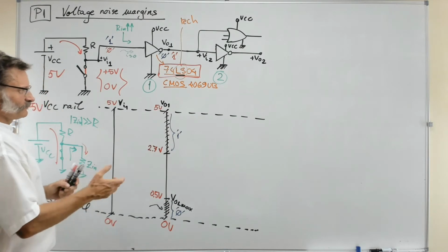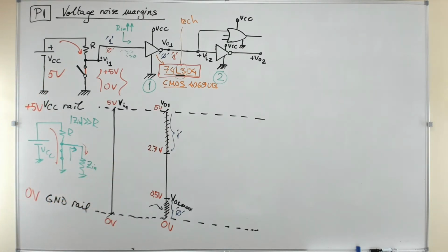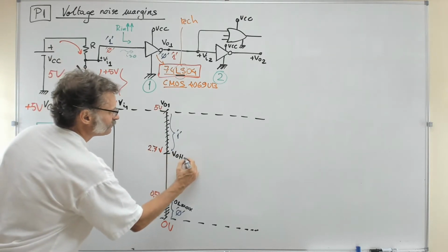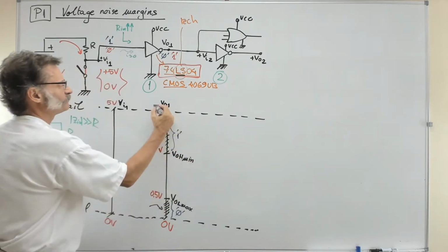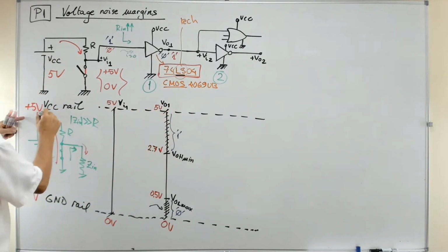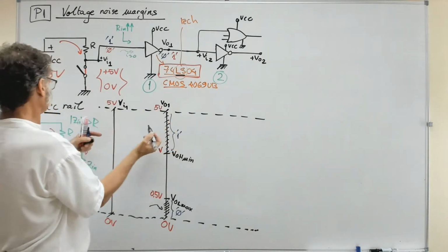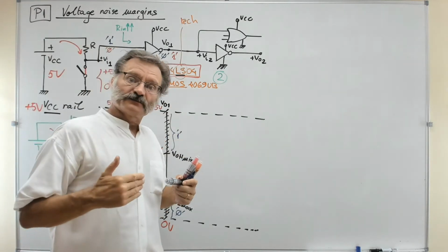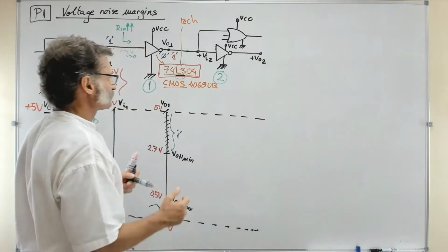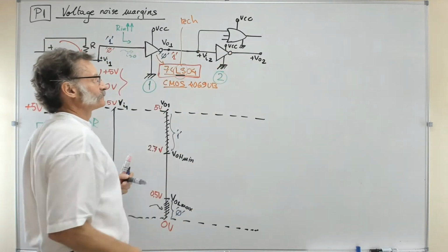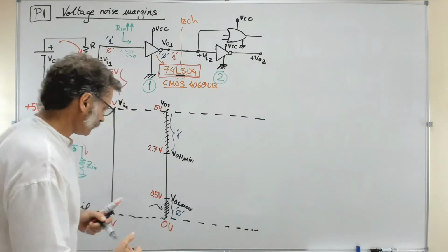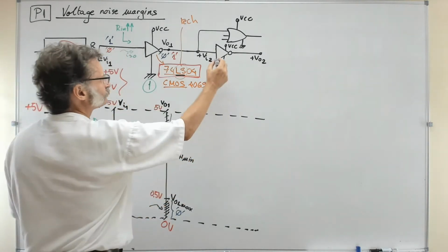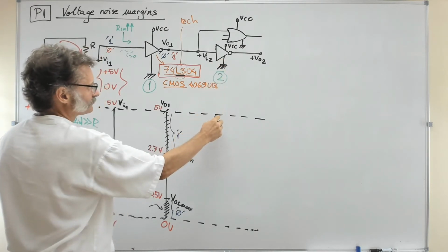So very well, okay. And now you can label that, you see, VO high minimum possible, because the maximum possible stays attached to the VCC, the top rail. So that's for a single gate. Now what happens here? You connect other gates just to generate a circuit, and normally you will have not 2 gates but many more, absolutely. So look at what happens here now.